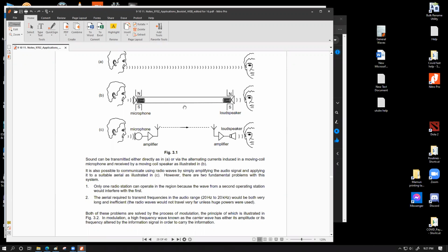So if we simply use the audio frequency of our voice, which basically falls within the radio frequency, because radio waves are basically the very last range of the defined electromagnetic spectrum. No matter how small a wave you think about, it can be considered a radio wave. So if we do use our voice signal frequencies, which is 20 Hz to 20,000 Hz, the typical audible range for human beings, and use that exact frequency for radio signal transmission, we require extremely high amplitude of those signals for it to be able to cover large distances, because the frequency is very low.